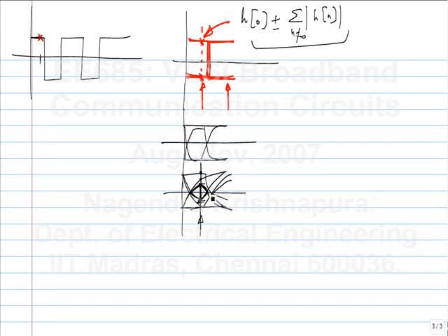So signal minus the ISI divided by the sigma of the random noise will determine the bit error rate. Then I can also point out that the horizontal opening of the eye is also of great importance in fact. Why is that?